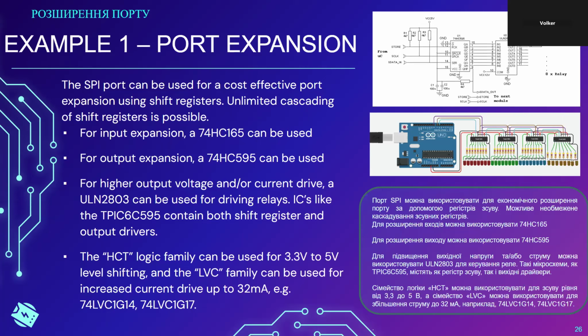Otherwise, like in previous processors, every time a byte arrives, the processor gets an interrupt and has to drop everything that it's doing and process that byte. DMA makes it unnecessary. So yes, modern microcontrollers are fast, and they have built-in tools that can deal with large amounts of incoming data. So yes, those conflicts can be avoided.